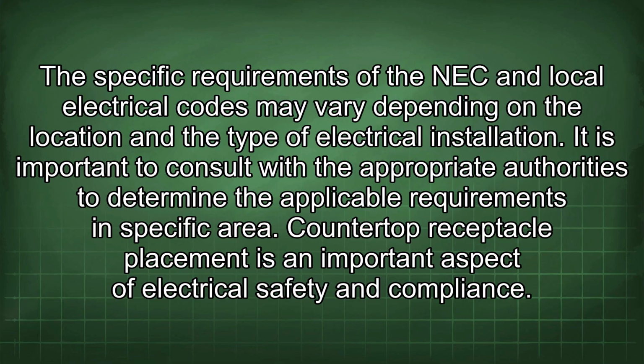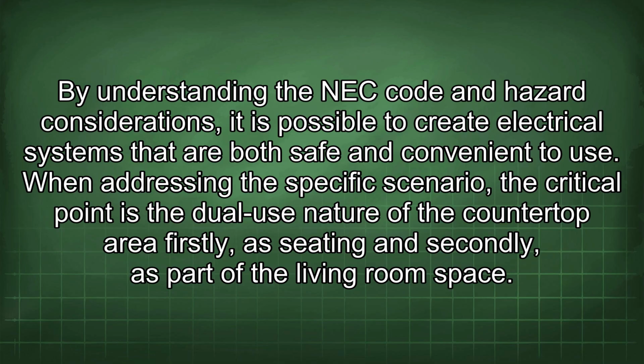Countertop receptacle placement is an important aspect of electrical safety and compliance. By understanding the NEC code and hazard considerations, it is possible to create electrical systems that are both safe and convenient to use. When addressing the specific scenario, the critical point is the dual-use nature of the countertop area, firstly, as seating and secondly, as part of the living room space.